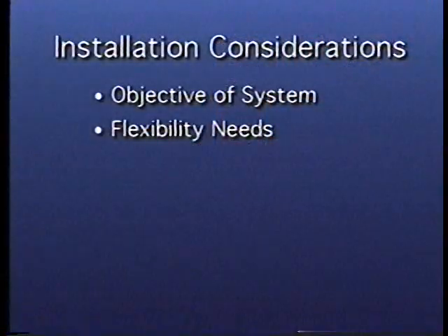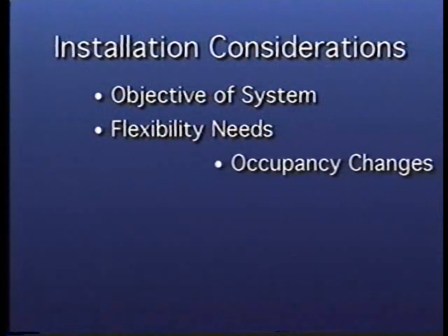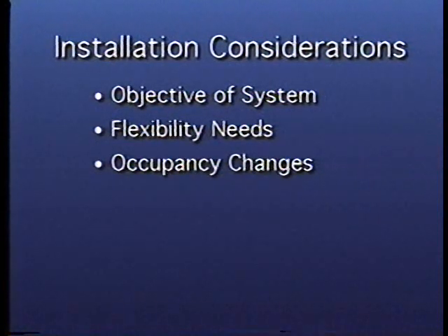In some instances, the owner may choose to provide the individual water flow detection from each tenant space as a service. This too affects the capabilities and type of alarm system chosen for the facility. The likelihood of occupancy changes can also affect the water supply requirements and the spacing of the sprinklers. If the building experiences frequent occupancy changes, you may decide to design the system for the greater hazard, in which case, no revisions to the sprinkler system may be needed when the occupancy does change.